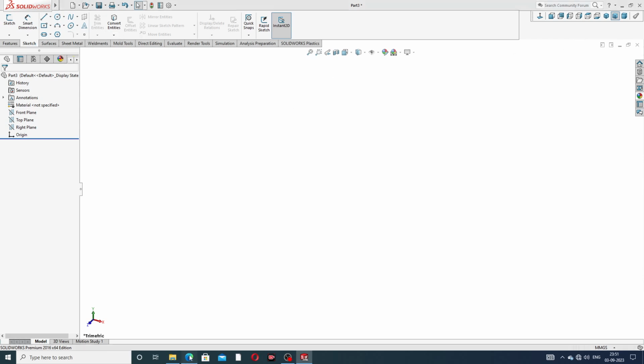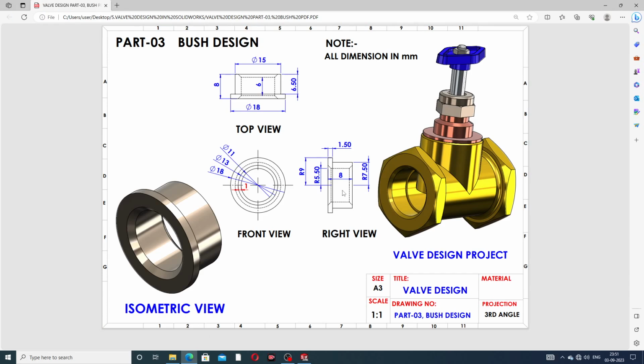And this uses the 2D drafting available here, and this uses the right view, and the right view is very important and correct. This length is 9mm radius. And this same is 18mm diameter, and this is 5.5mm radius.